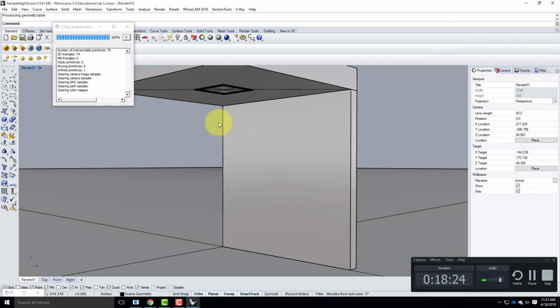And it's really important that you understand that the V-Ray light has to be in the scene that's doing the rendering. So all the lights that we're going to insert into our final renderings are going to be in that master site file, just like the sun. You don't put the sun in the block that you're bringing in. You put the sun in the final rendered version. So I'm going to put the V-Ray light in the final rendered version as well.